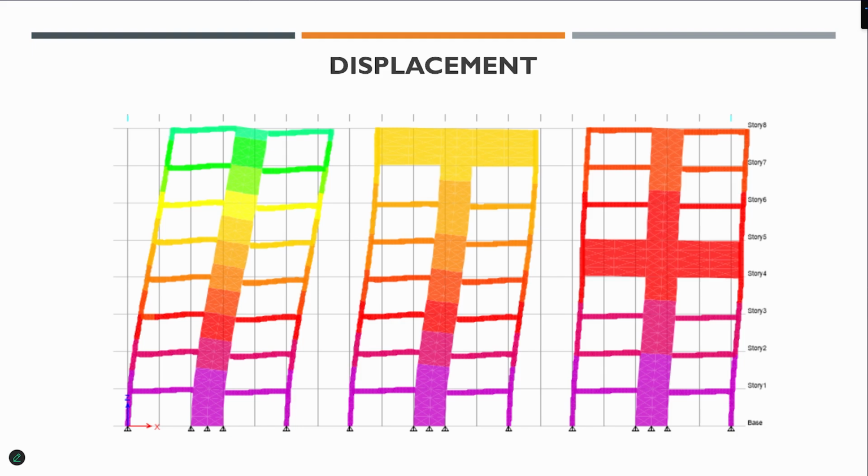And when you divide by the shorter length, because the columns above are not participating in the outrigger effect, only the columns below are participating, and they are shorter in length. So simple question, EA over L is the stiffness. So if the L is shorter, the stiffness will be larger. So it becomes large. So that's exactly right. And this is an important note because you can play with this when optimizing the location of the outriggers.